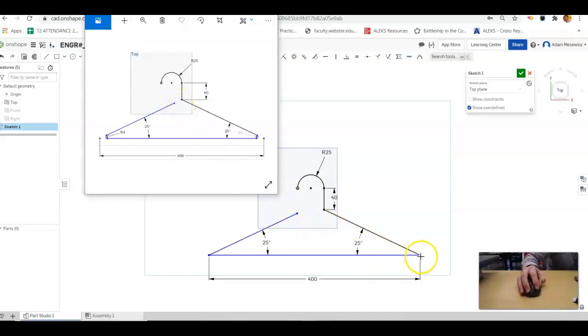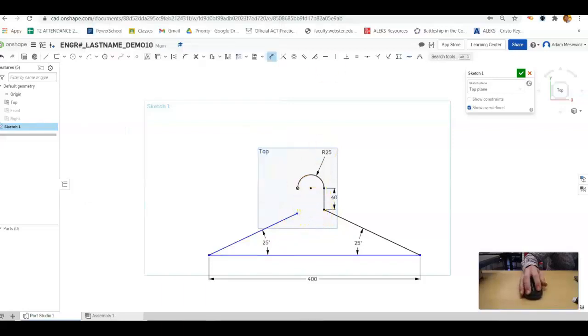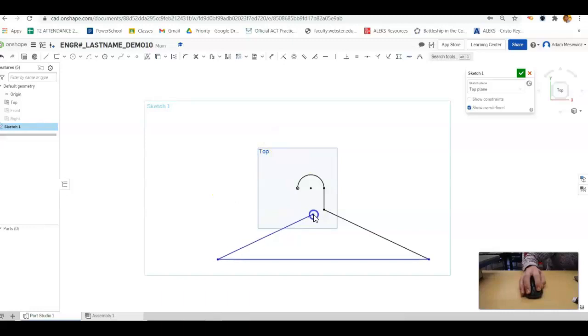And so obviously we have these sharp edges, we're gonna have to fillet those, but we're gonna have to move this point to be closer to where we're at here, or else this hanger is really not gonna be structurally sound. So to do that, because we haven't put any sizes or dimensions on either of these legs of the triangle, if we press escape to get out of our dimension tool, we can actually click on this point and move it to exactly where we want. And it's going to keep all of those dimensions that we already set.